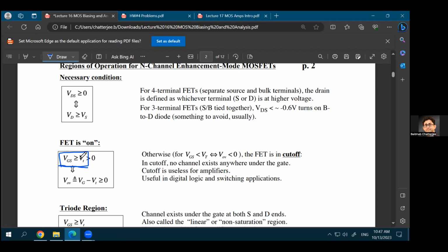For a P-channel MOSFET, we'll see how that equation is slightly changed, but in most cases, you'll see that there is a direct correlation between the equations for the N-channel MOSFET and the P-channel MOSFET. So for now, we'll only concentrate on the N-channel MOSFET and look at all its equations. For the P-channel MOSFET, I'll tell you how to find the correct equations from the N-channel MOSFET equations. So for now, don't worry about the P-channel device. For the N-channel MOSFET, this is what your equation should look like when the device is on. And again, VGS has to be more than VTH.